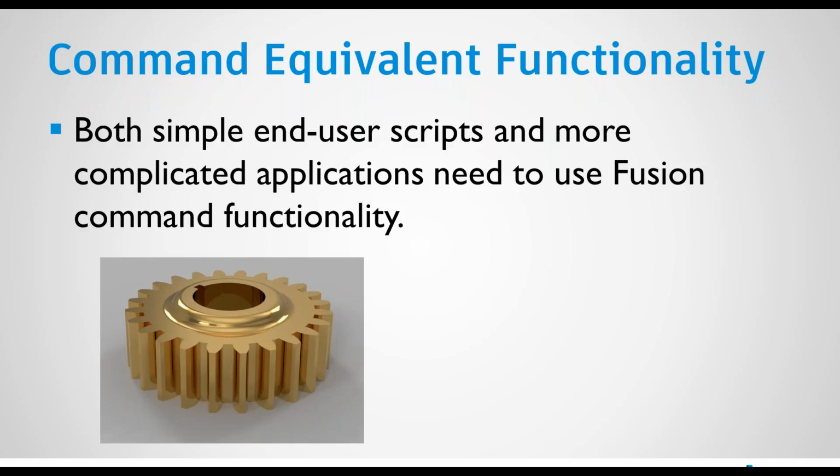I want to create a gear, and I can look up on the web and find out the formula for how an involute tooth is created, and get out my calculator, maybe write a little function in Excel that would calculate points along that involute. And so I get the points, I fit a curve through those, I mirror that curve over, so now I have the sides of one tooth, right? And I create an arc along the top, I extrude it, so now I have one tooth on my gear.